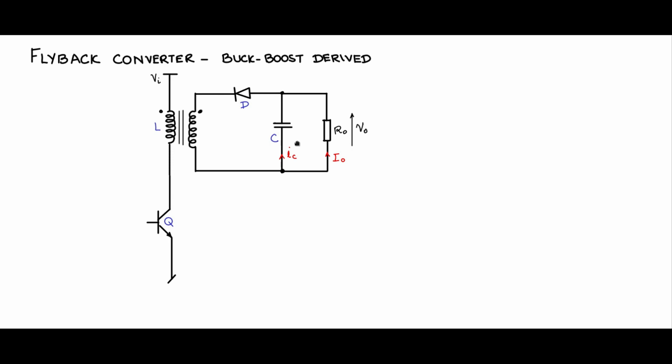is still maintained. We can do some more modification in the circuit to make it a bit more attractive. So what we can do is first remove these markings, this diode and the dot polarity. Let us reverse the diode. If you reverse the diode, I should reverse the dot polarity, so that when the non-dot end is positive, the diode should be on. And if you reverse the diode, the capacitor will get charged in this direction, plus and minus, and we will have, as measured in this fashion, a positive voltage.